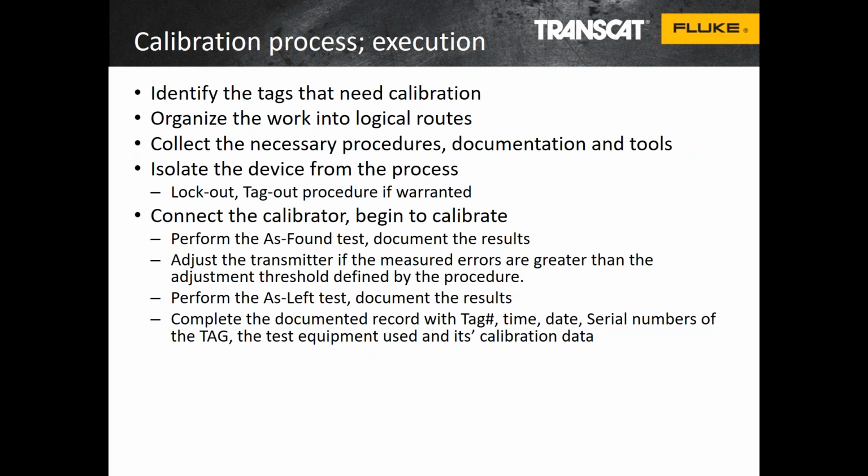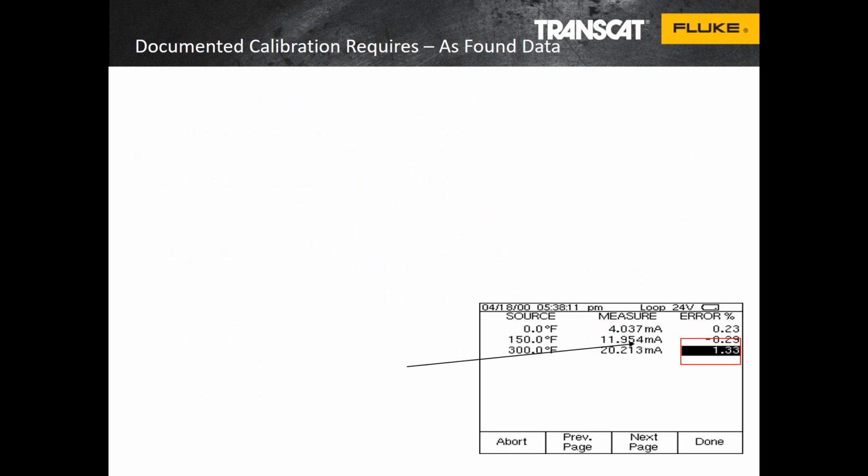Complete the documented record with the tag ID number, time, date, serial number of the tag, the test equipment used, its calibration data, and of course, the person performing the work. Next.